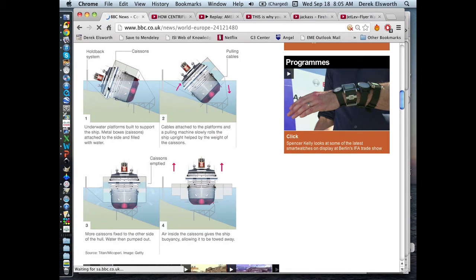We know how the center of gravity here would provide a moment about this point, and so if we were calculating this and pulling on this, then the force that you have to apply here you could calculate by knowing what the physical weight of this ship is, what the extra weight of this container is, and just by taking moments about the rotation point, you'd be able to figure out exactly what's happening. I suppose you'd also have to take in the fluid pressures that are acting on this side and this side, but you know how to do that.